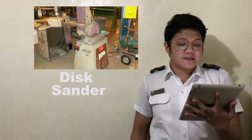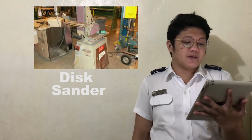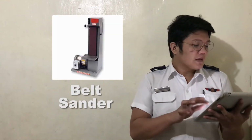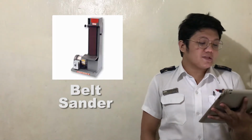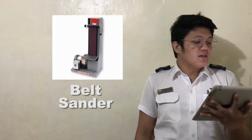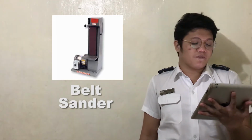The combination disc and belt sander has a vertical belt sander coupled with a disc sander and is often used in the metal shop. Next one, belt sander. The belt sander uses an endless abrasive belt driven by an electrical motor to sand down metal parts, much like the disc sander unit. The abrasive paper used on the belt comes in different degrees of grit or coarseness.